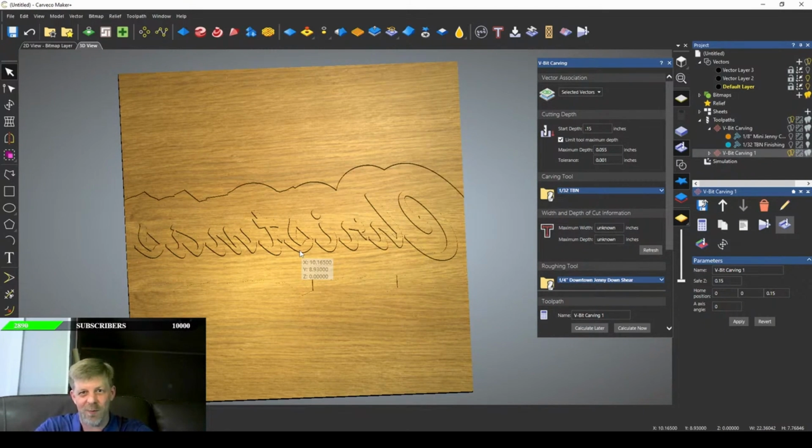If the pressure is only in one spot, or only in a particular area, it can actually crack the board in half, or crack your piece in half. And that's something that has definitely happened to me. Beware of that. Make sure you have even clamping pressure when you're putting these pieces together.